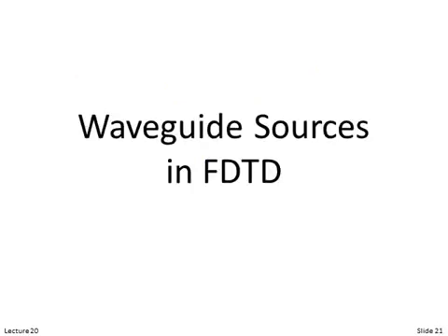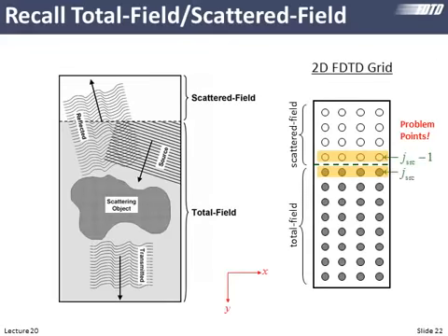Okay, so we discussed some quick theory with slab waveguides. I stepped you through quickly how to analyze a slab waveguide to calculate the modes and gave you all the MATLAB code to do that, and hopefully just enough understanding to sort of believe what's happening in that method, and you can use that code to calculate sources or calculate the modes. So given those modes, now we need to figure out how to include that in finite difference time domain as a source. So we're going to inject these sources the exact same way with a rather minimal modification to our total field scatter field framework.